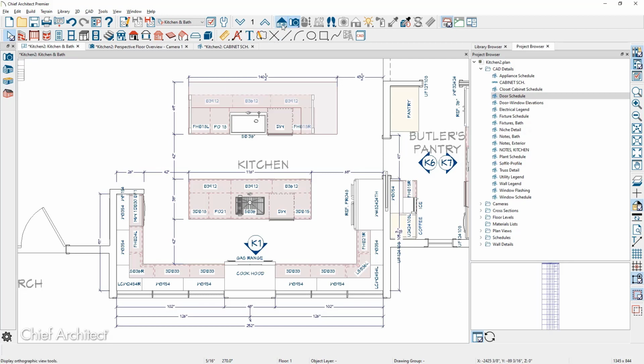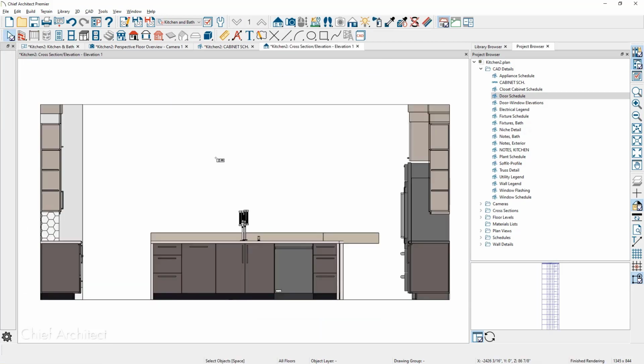I'm going to use the wall elevation tool and cut an elevation right through the island. When you generate the wall elevation view, it's looking for the furthest wall behind it. I have an invisible wall, so you're actually not seeing the final wall, but you are seeing other things like the other island behind the view. So what you can do is back clip the cross-section view.